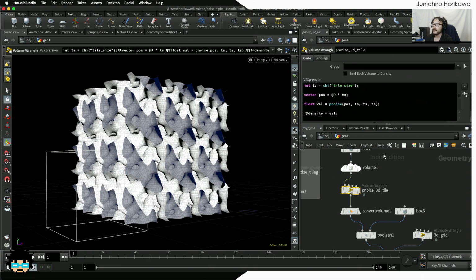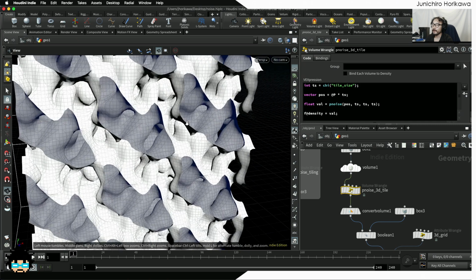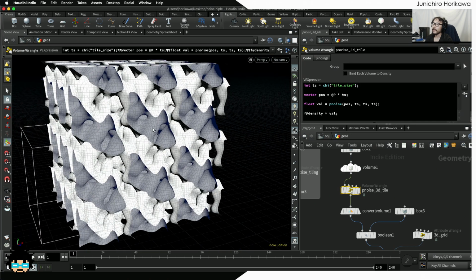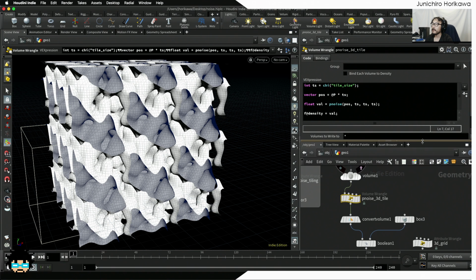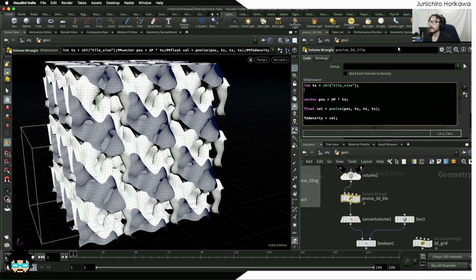And probably it will be interesting if we could animate this geometry as well, using some shift related value like we did for the noise exercises. Now to do that, instead of using a vector 3, we could use a vector 4 value by adding a shift value to the fourth coordinate. Okay, so I'm going to first create a shift parameter. Let's call that float shift.